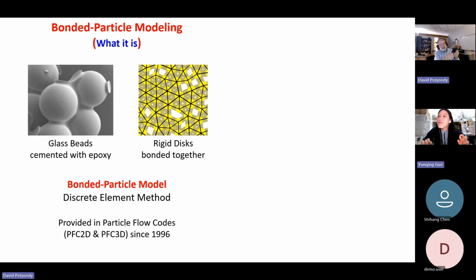Well, this case is most likely created by powder compaction. So what they do is they take a powder and they squeeze it together into the shape they want. And then I think they would also heat it, and what happens is the powder fuses together to form a solid material. And this way you can make very complicated shapes.